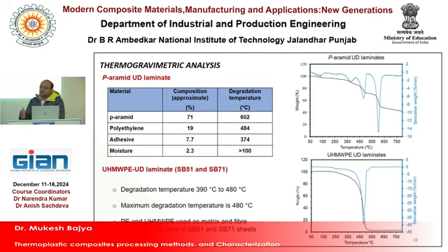And what are the other constituents? Sometimes you have added some nanoparticles during the composite manufacturing. From the TGA you can see the percentage and uniformity of the dispersion of those materials. You can also confirm those kinds of things from thermogravimetric analysis, because in TGA you use a small portion of that composite. You can take a small portion from 4 to 5 places, and then you can see whether it is uniform or not. That is also a confirmation test.